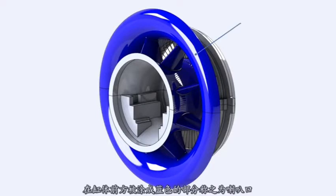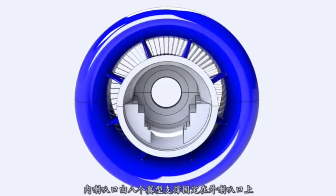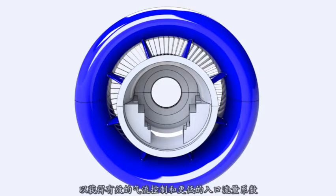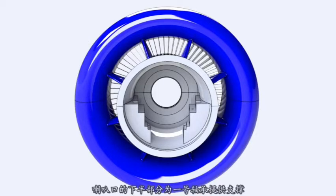The blue painted section at the forward of the casing is called the bell mouth. The inner bell mouth is positioned to the outer bell mouth by 8 airfoil-shaped struts. The bell mouth function is to direct the air normally and uniformly to the inlet guide vanes for efficient airflow control and better inlet flow coefficient. The lower half of the bell mouth provides support for bearing number 1.